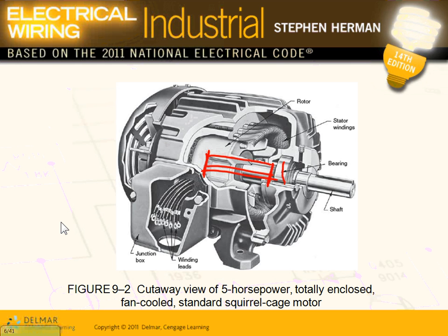And then you have your wires, the 3-phase wiring here, bringing you 3-phase. Low maintenance, nothing. There's no coils. It's a chunk of metal inside a coil, and it rotates because of magnetic field. So that's the cheapest motor you're going to get. You are familiar with, by the way, motors, guys, you're going to have induction motors, you're going to have synchronous motors, and you're going to have DC motors. These are the most superior motors in the power industry. So all the air handling units that you have, rooftop units, they're going to have some type of an induction motor.